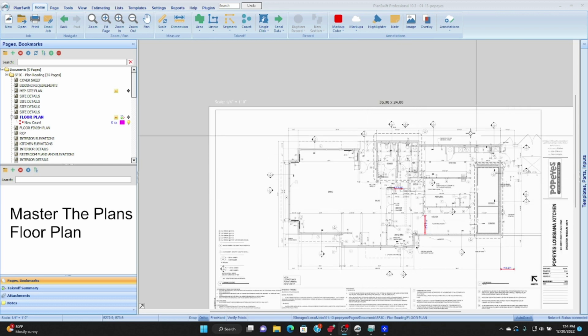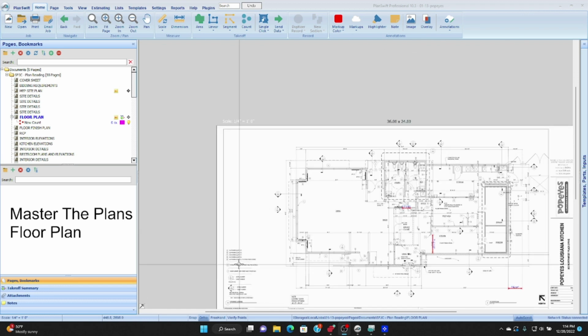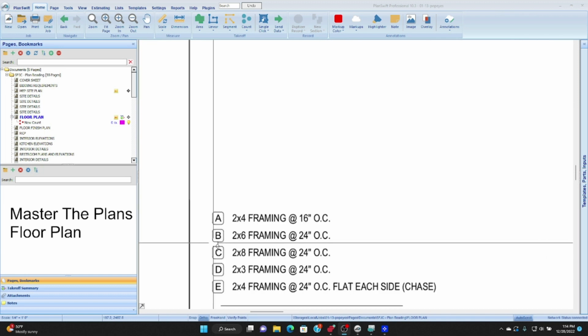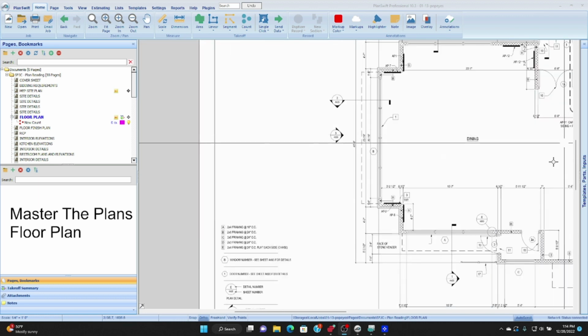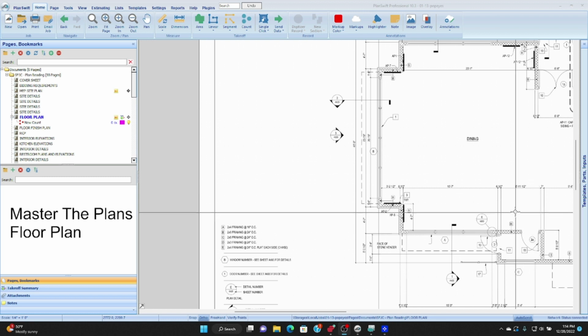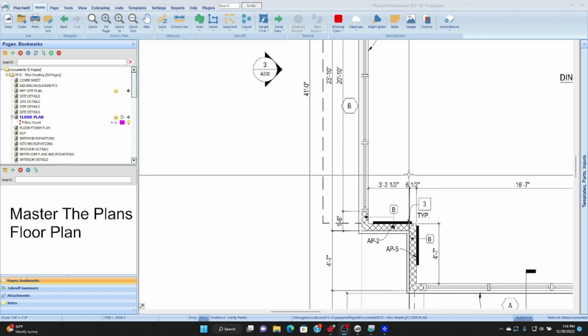And here, the floor plan's job is to help us measure how many linear feet of each type of wall, based on our legend and what we are instructed in terms of maybe even the specifications on the types of walls and what they're made out of. Okay, and now, very specific to many floor plans, they're what we call highly dimensioned.